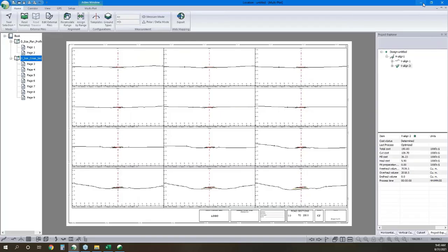Now, the way this behaves is going to be based on how frequent the cross sections are modeled in the software. And quite often, in order to get reasonable volumes and rendering of what we're working with, we're going to want more than just cross sections at certain intervals. So you're going to want to include cross sections being calculated at your beginning and end of curve, where templates change, culverts, anywhere that there's something notable going on. But you probably don't want all those intervals included in your cross section.